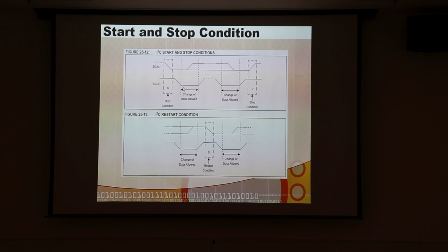And if you think about that, that makes sense because you're using open collectors and the line's pulled high, so the idle condition is the clock line's high. So normally in idle condition you wouldn't expect the data line to get pulled low. The only time when that happens is when you're issuing a start command.